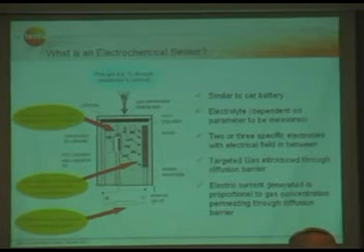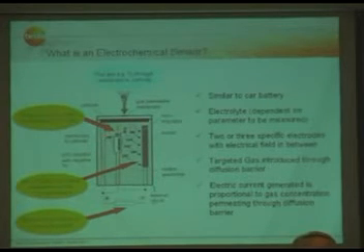The O2 sensor is very specific compared to toxic sensors like NO, SO2, whatever, because if you don't use the analyzer, the highest concentration, like 21% oxygen of the ambient air, will get through the sensor. This is why the oxygen sensor will normally be used up first if you buy the instrument, because if you don't use the sensor, the highest concentration gets through it and the reaction is taking place.